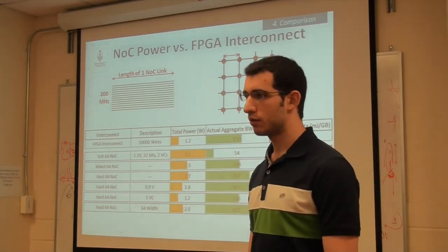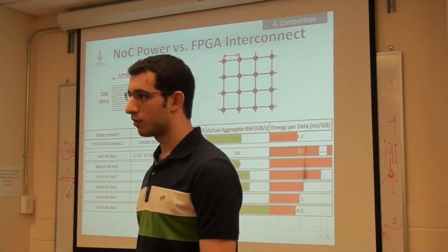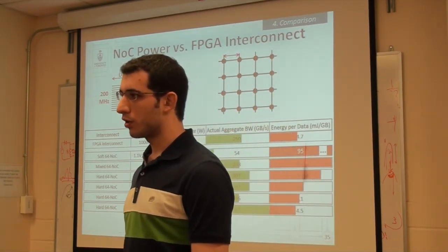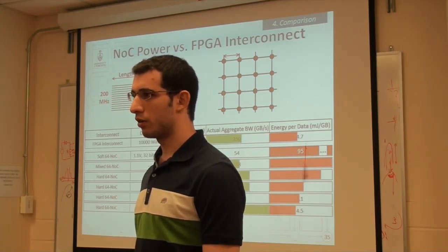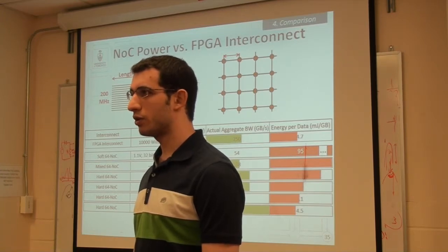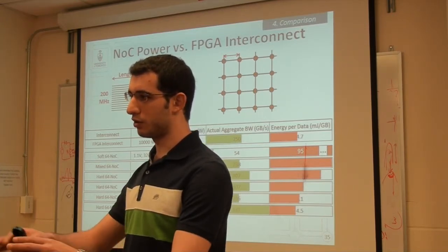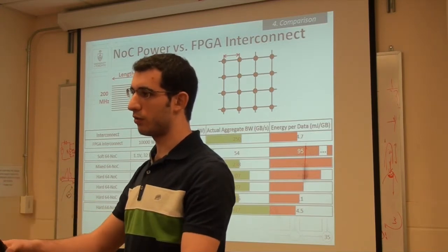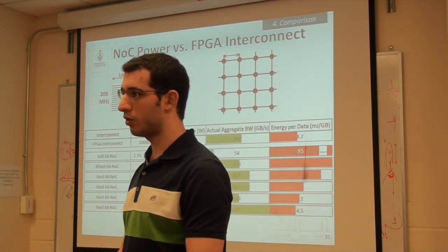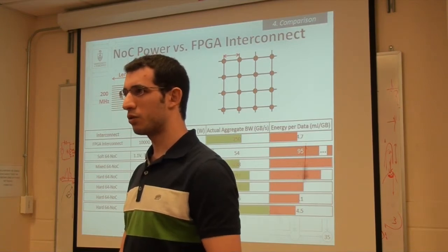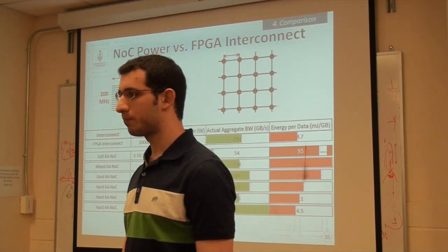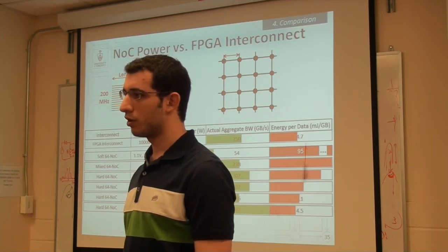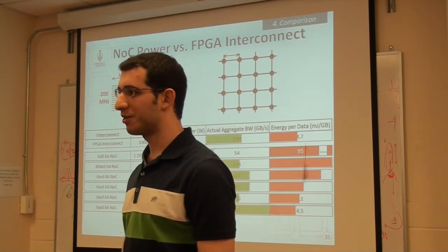Because you're running at a higher clock speed, I'm actually curious what proportion of power comes from clock power? Clock power. So we estimated clock power, and it's included in the numbers there. It wasn't much. We have basically 64 nodes on the FPGA, so it's a relatively simple clock tree when you compare it to FPGA clock trees. I think it was close to 5%, something like that. So the router is idling, waiting for information, and it's basically just consuming clock power, it doesn't consume much of it. Yes. Oh, that's another graph of that.